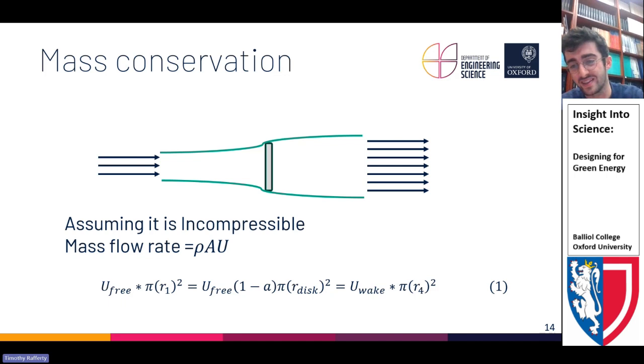I will relinquish. These are really good ideas. This is a hard one. So we describe it as something called the mass flow rate. So instead of just purely conserving mass, we're going to conserve it at a rate. And so that comes out as the density times the area times velocity, which you can kind of see links back to mass, how we've just gone through it there, where we've said, oh, it's mass divided by volume is density. So what we're actually wanting to conserve is density times area times velocity. And so if I want to say, well, point one, when I'm here, well, the mass flow rate here should be the same as the mass flow rate in the middle. It should be the same as the mass flow rate at the end.